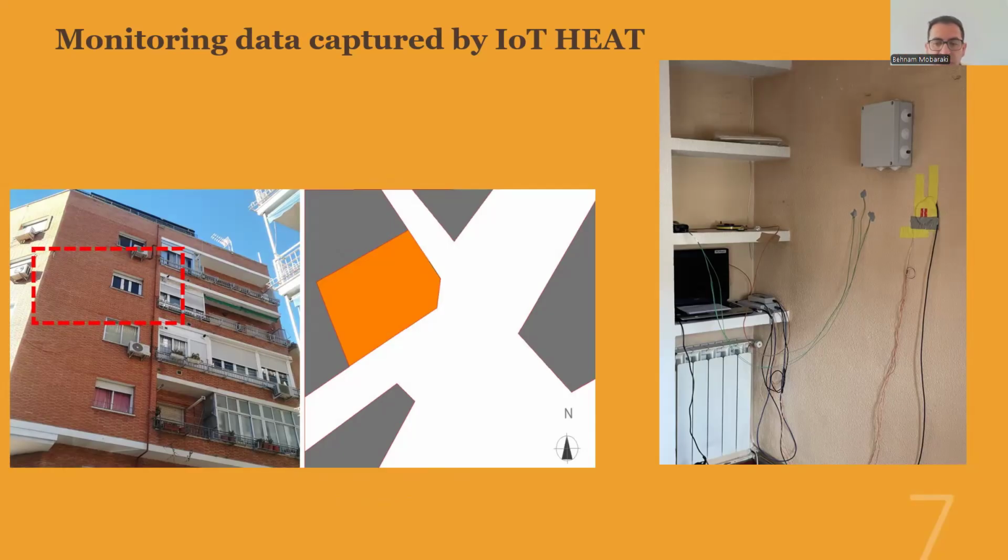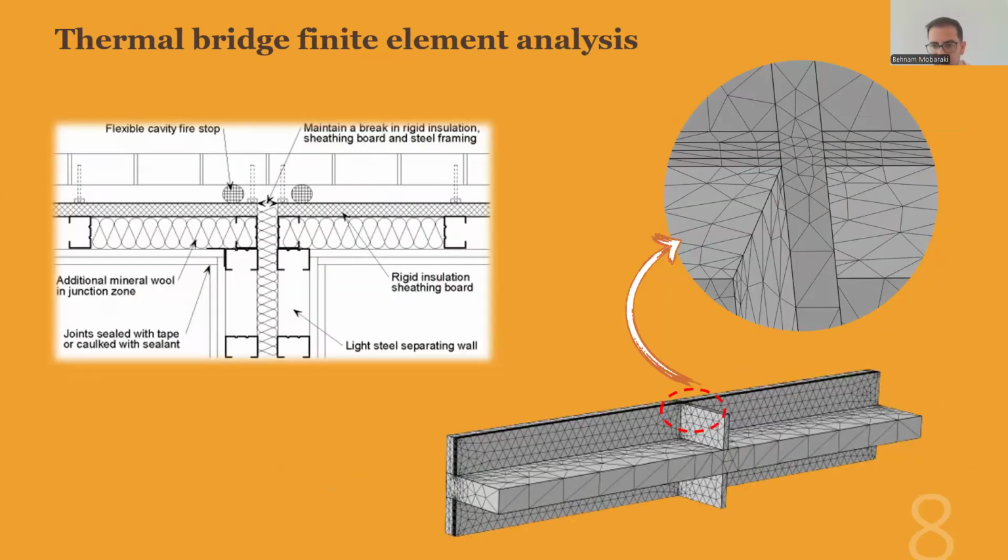In this research we have focused on quantifying heat flux, temperature distribution, and linear thermal transmittance across key envelope junctions. In this way, we could study the junction, or thermal bridge, weaknesses in a residential building.